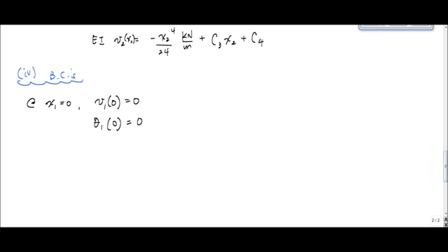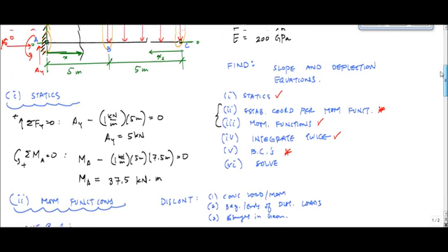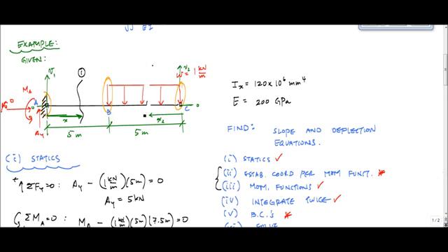Now the boundary conditions for x2. We can't look at this beam over here and say there's anything that really stands out. The only thing you have is the interaction between the moment function at 1 and the moment function at 2. Because the deflected shape has to be continuous, you can't have some step or something, right? It has to be continuous.